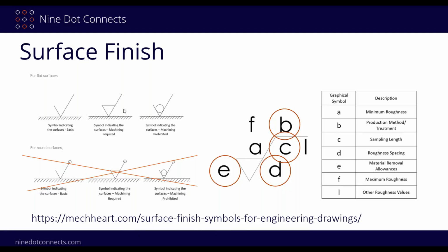Here's your symbol over here, and there are various things that they have, since there's a standard for this, and you can kind of see what they have. Altium really left F, A, and L out of this whole equation. They have to do with roughness values because, quite honestly, we generally don't work with roughness. Maybe there's copper roughness, but in the end, our end product has a solder mask on top of it, so we're not really dealing with roughness, unless you are using a CNC machine to cut through copper, or to mill out around the board for a panel. That's the idea I think they're shooting for with this.